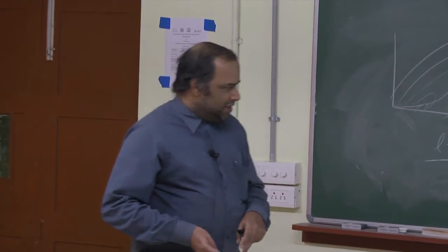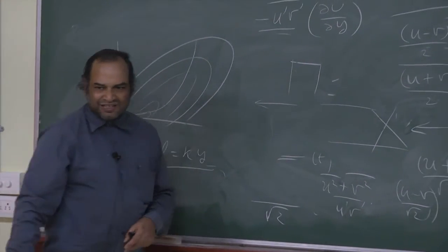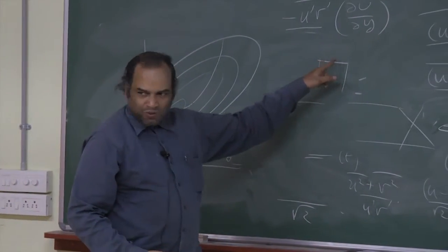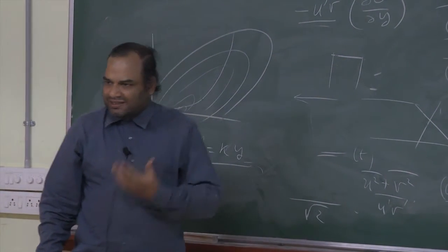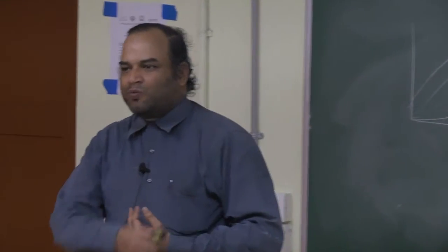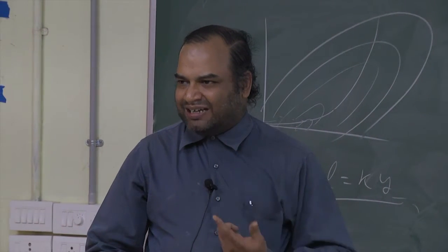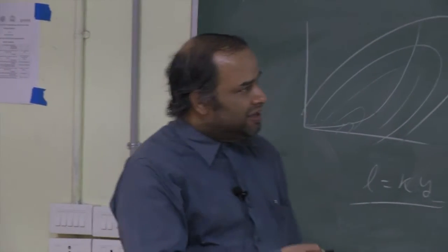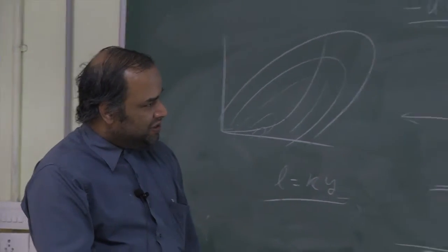Now what will happen, imagine your hot wire is a certain size, right? Active length of the hot wire is this much. It's going to do an average over this length. Imagine if my wire is larger than my eddy, it's obviously going to smear it out. It will not give a faithful representation of what is contained in that. As a result, especially when you go close to the wall, you expect your active length of the wire, if it's a Wollaston wire or a tungsten wire, is the full length itself, to be reasonably small. How small? Well, there is a slide which says how much it should be.